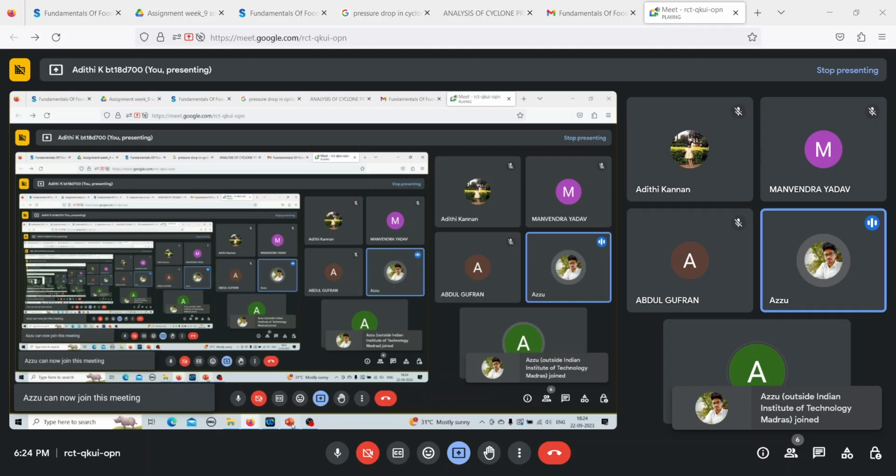On the other hand, separating fat from water is easier because of the density difference, so you can collect them differently. Oil, because of its lesser density, will probably be collected at the center and water will be thrown out. So you need at least one of the phases in liquid form for centrifugation to take place.